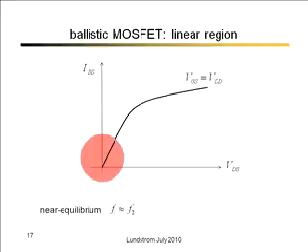Okay, so now we have everything we need to calculate the IV characteristics of this MOSFET. It gets a little bit involved to do the whole IV characteristic, so I'm going to concentrate on the 2 limits: the low drain voltage limit, where it behaves like a voltage-controlled resistor, and then the high drain voltage limit. So let's look down here first.